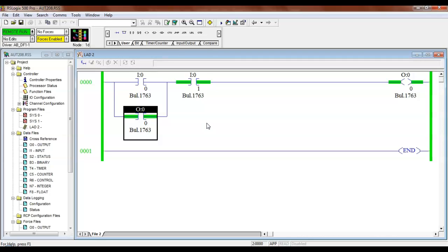But what I just did is write a program in ladder logic, which is a language that I understand. But my PLC has no idea what ladder logic is. All it knows is ones and zeros. So what happened when I downloaded it to the PLC, the application that I'm running compiled it over to binary before it sent it to the PLC.